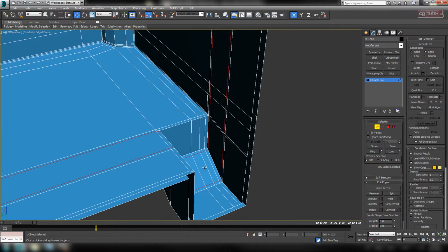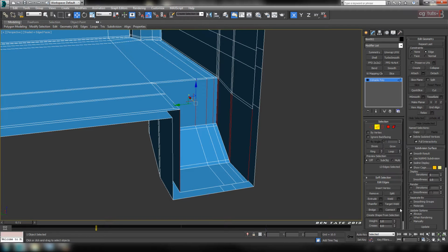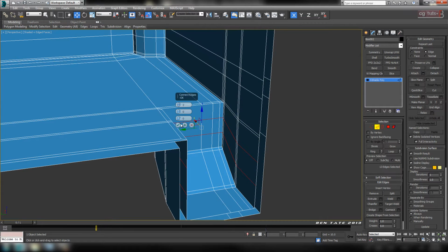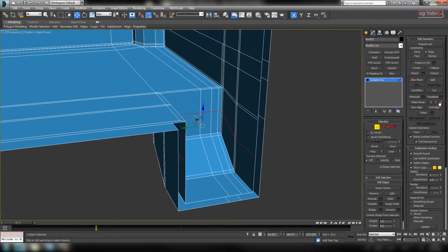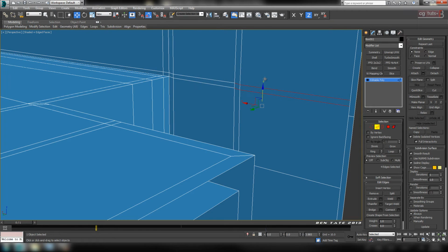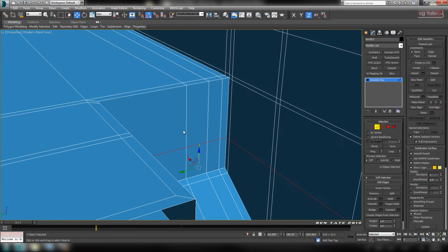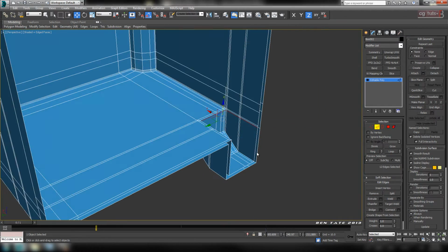And we're also going to need to support the shape here around the inside. So let's add a loop right here on these edges. Connect that up with one segment for starters, and we can make planar on Z and just move that up. Okay, we got these edges here kind of twisted down, so let's actually straighten those out quickly. Let's grab these two and these two, and we'll smooth those up a bit. Let's turn our edge constraint off first. Slide those up until we kind of straighten things out, like so. Okay, now we'll reselect this edge, loop it, and just move this up. Right about there. That should be fine.